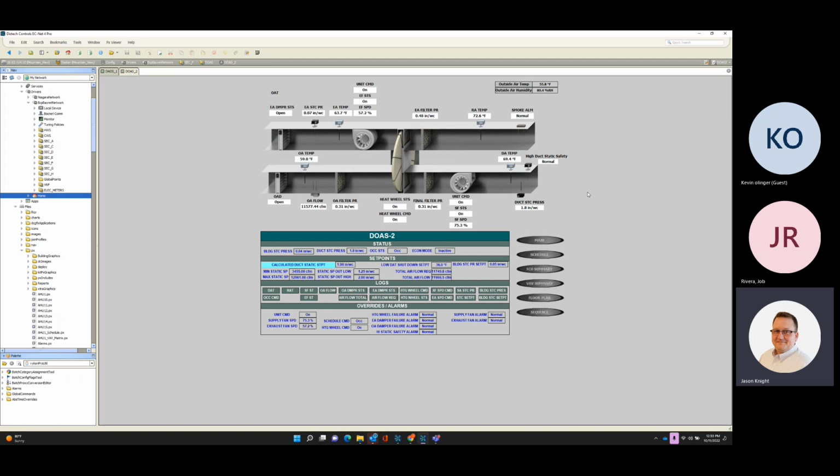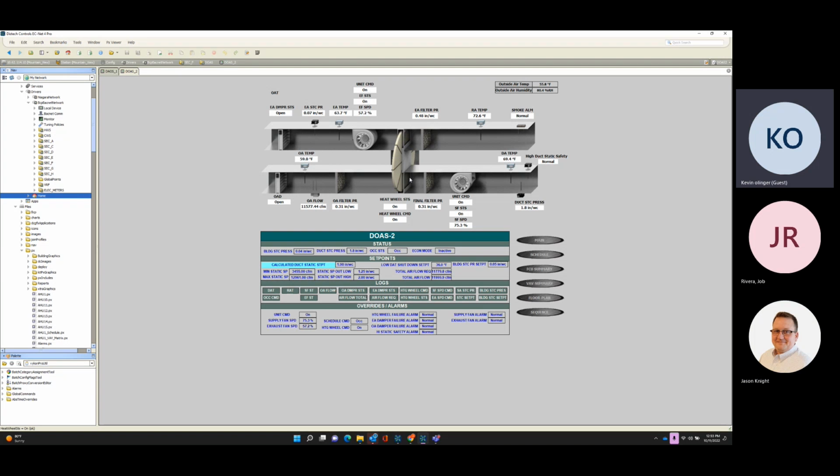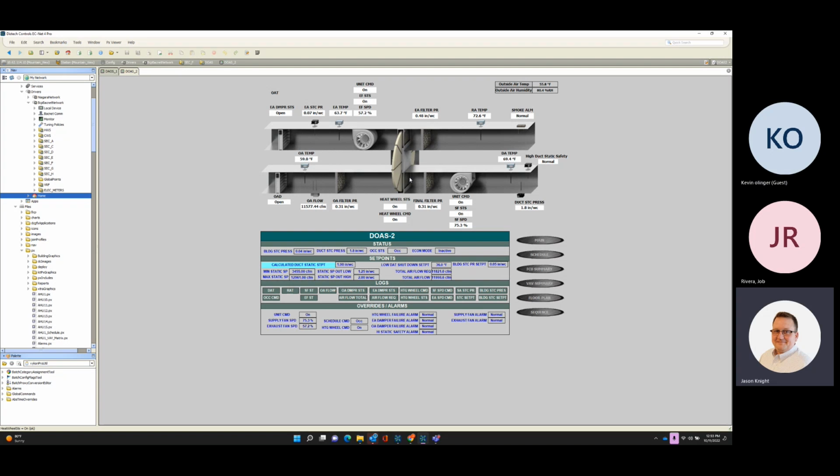The original spec said to maintain a discharge temp between 70 and 75. And I was like, okay, well, the unit that you bought doesn't have a modulating wheel speed. So how am I going to make a reset between 70 and 75 degrees when the wheel is either on or off? And then the engineer came back and said, well, you're not. Just turn it on or off and disregard that part of the spec. And okay, what turns it on or off? What are the conditions?